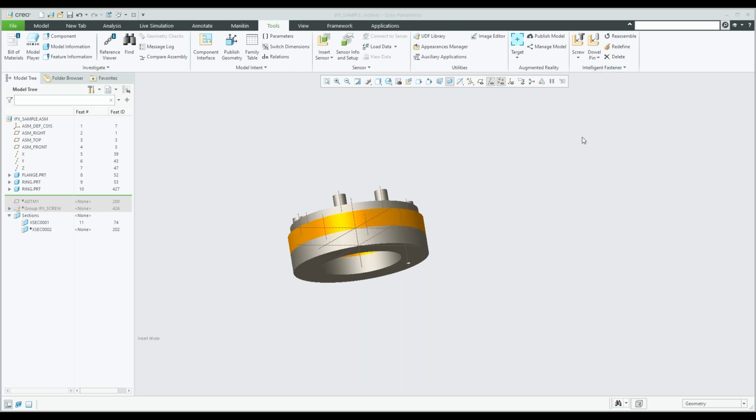Okay, so the next question is about IFX and does it work with Windchill? It certainly does. The only thing you have to do is take those components and those tables, and put them inside of Windchill. So you will use this instance creator, and you can create the instances of the bolts and nuts that you use and put that in Windchill, or you can put everything in Windchill. But you'll use the instance creator for that. So yep, you will do it like normal library parts. You just have to export it from the IFX catalogs and put that into Windchill.